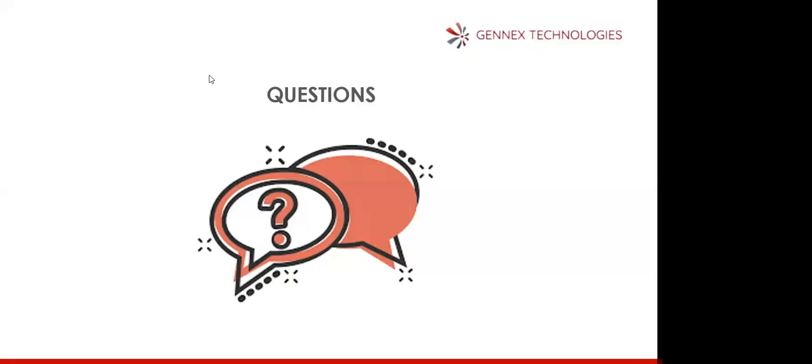We will know the symbol of each, either it is DC surge or AC surge. Then the ratings we want to check are the voltage and the current the surge can handle.